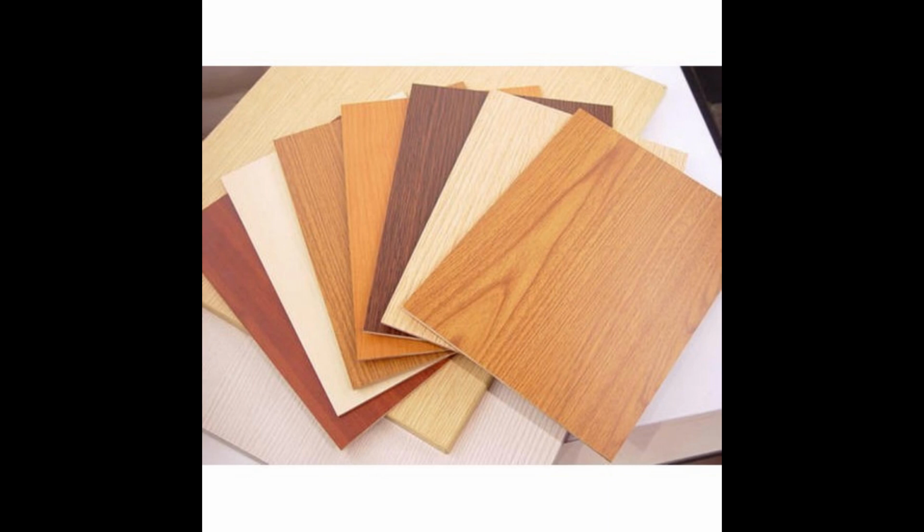All plywoods bind resin and wood fiber sheets, that is cellulose cells that are long, strong, and thin, to form a composite material. This alternation of the grain is called cross graining and has several important benefits. First, it reduces the tendency of wood to split when nailed at the edges. Second, it reduces expansion and shrinkage, providing improved dimensional stability. And thirdly, it makes the strength of the panel consistent across all directions.